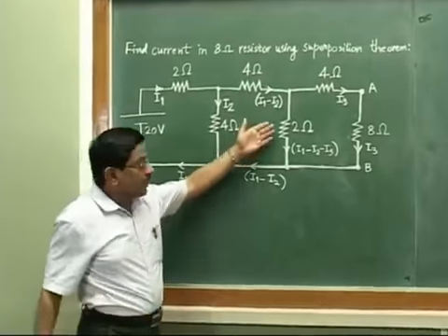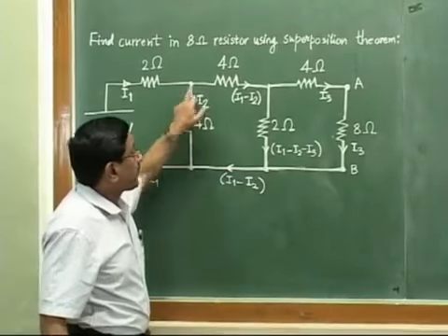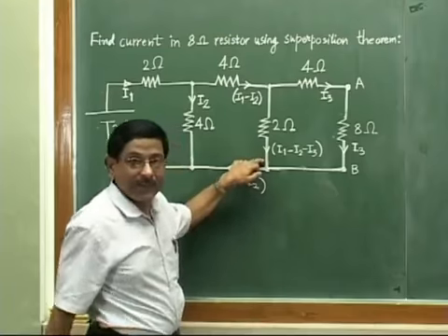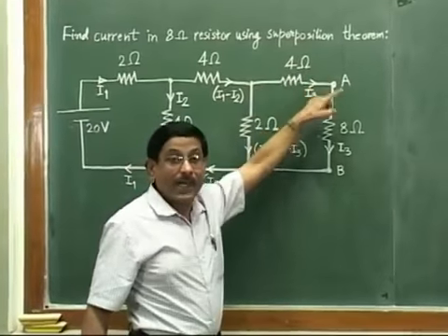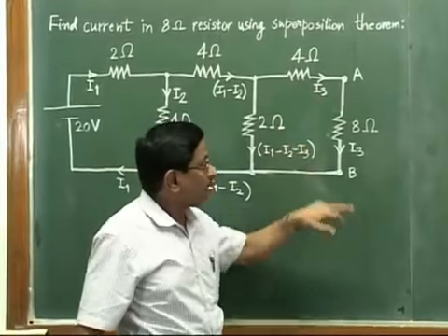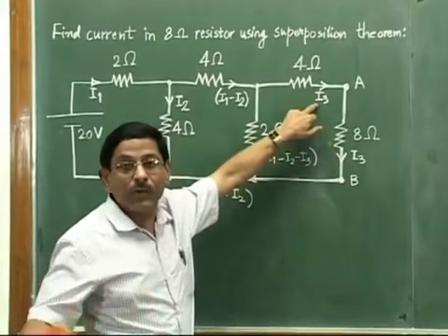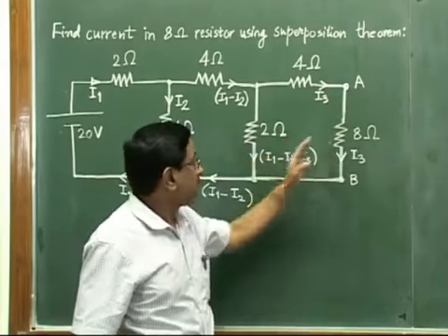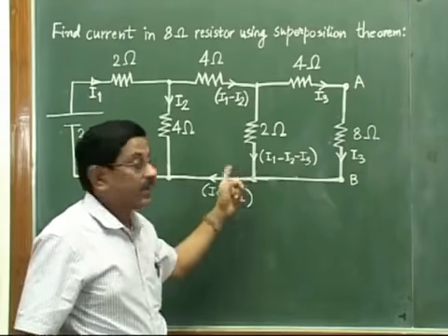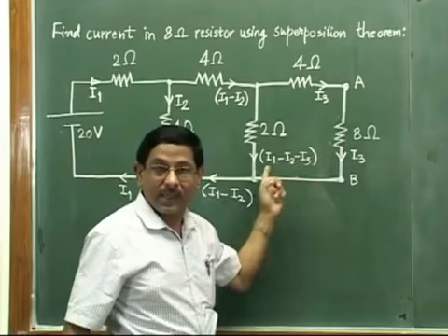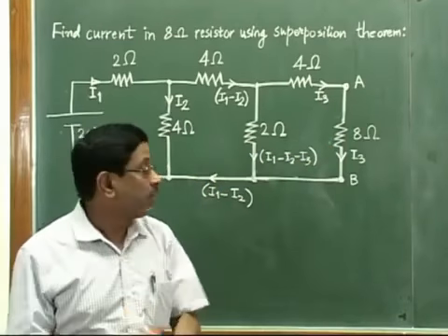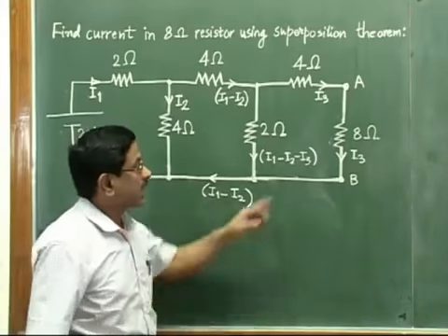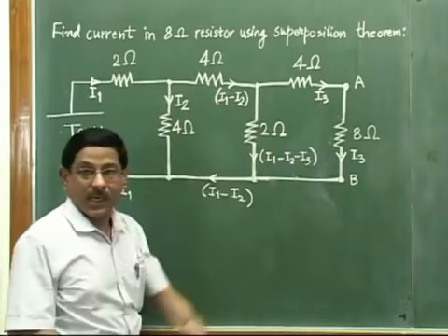Keep in mind that here I have taken I2, so this was I1 minus I2. Somebody may take I3 here. That is valid, he can do that. The current moving ahead in that case would be I1 minus I2 minus I3. But why have I purposely taken I3 here? Because when we solve the equations, we directly get the value of the variable I3. Otherwise, after solving the equations you have to perform one more calculation: what is I1 minus I2 minus I3? So this is the current distribution.